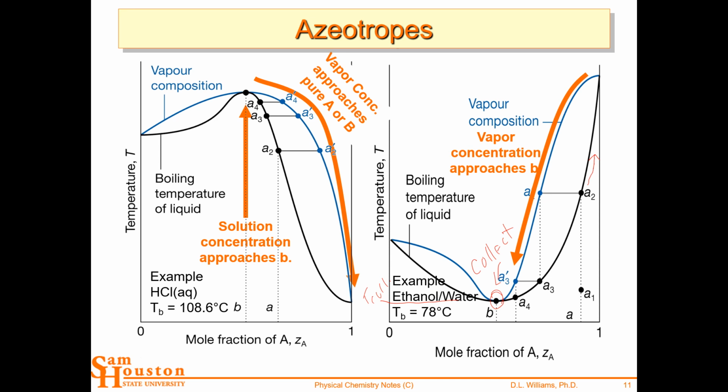And so just take the TX phase diagram when you have an azeotrope and split it in half at the azeotropic point, and then you just have two independent TX diagrams. And you've got to decide which one you're in. Like it? This is fun stuff. I like the TX diagram. Okay. All right, so look at all of that. I'll try to put some terms together with these to quiz you for this week's homework.